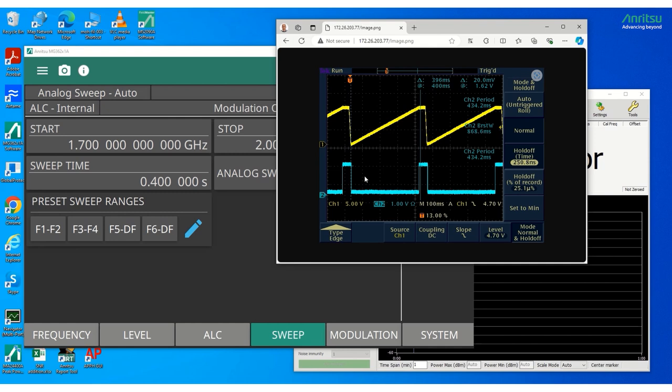Output power from DUT, which is the bandpass filter in our case, is measured by the sensor with every trigger and is displayed in scope mode. Power sensor in scope mode should then show the amplitude response of our bandpass filter. This is going to be our measurement process.